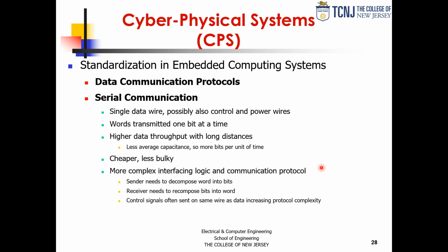Since semiconductors are faster and we can run at higher data rates, it's become more feasible to serialize things that were parallel before. A classic example is the evolution of parallel interfaces for disk drives to serial. We use today nothing but serial ATA.